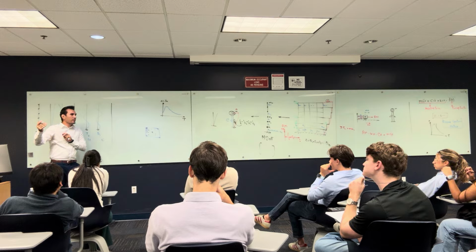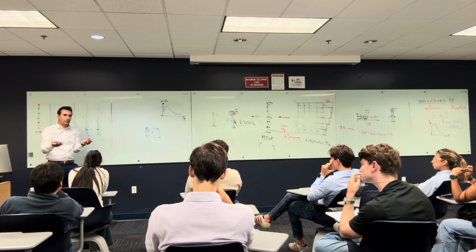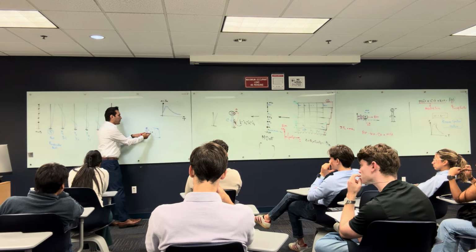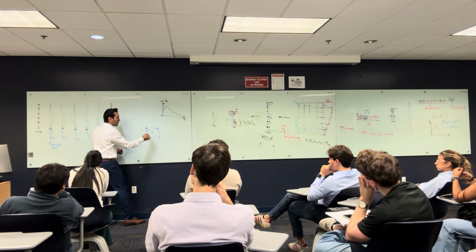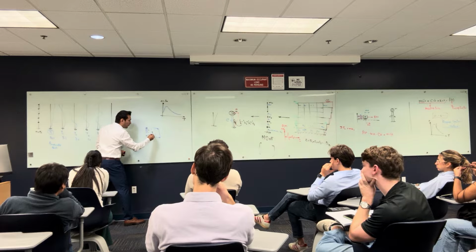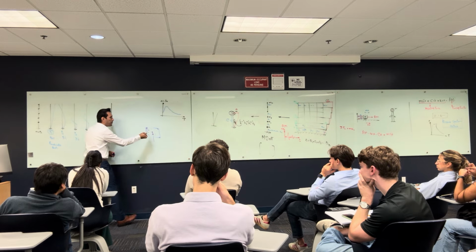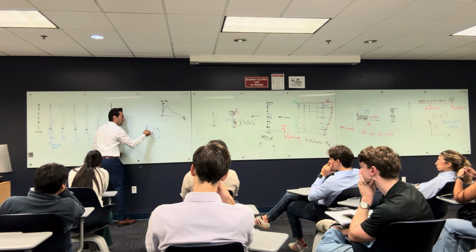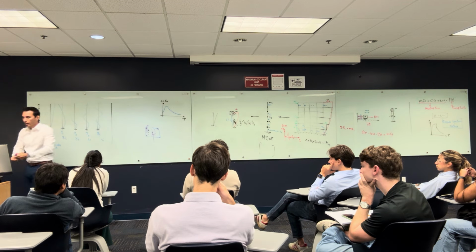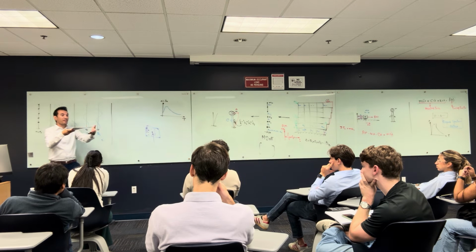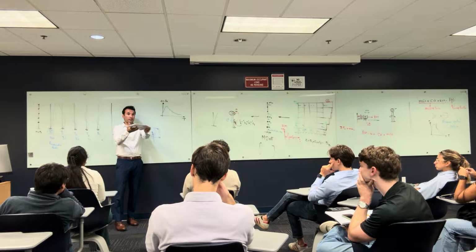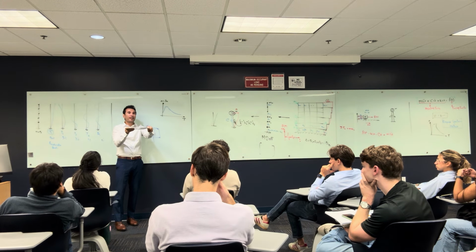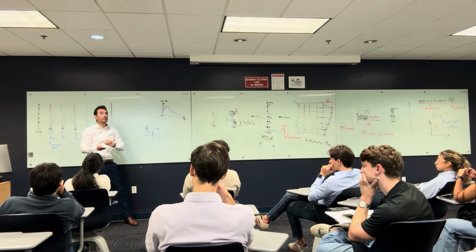By the way, have you guys done the center of mass calculation in dynamics or other classes? This is how you calculate it, the same way to get the center of rigidity. And then if an earthquake happens, usually the force of the earthquake hits at the center of mass and makes a moment around the center of rigidity. So basically, I want you to imagine with me, this is my slab system, and you have a very, very stiff element here, and there's a load that's hitting this slab. What is gonna happen to this slab? It's gonna be shaking like this. So that is a torsional mode. You don't want this to happen in your system.